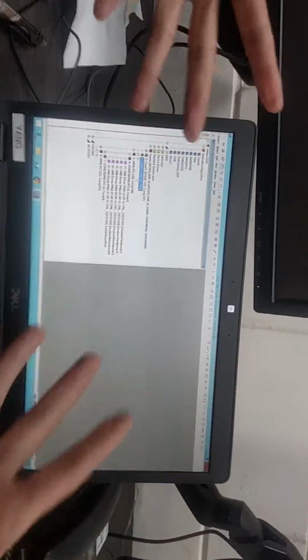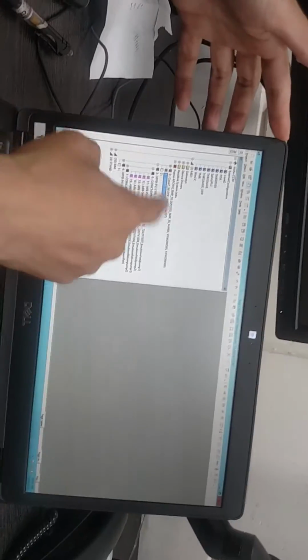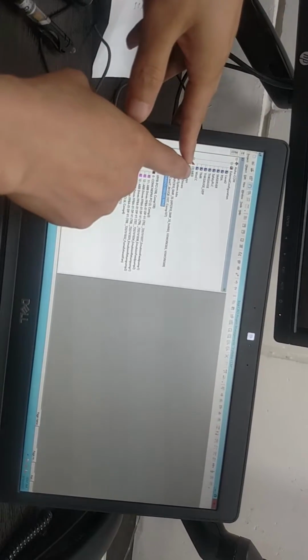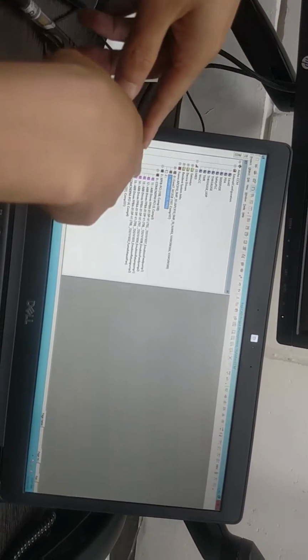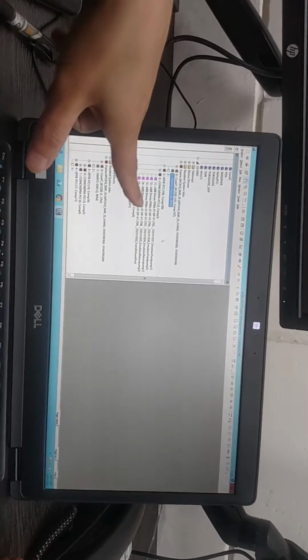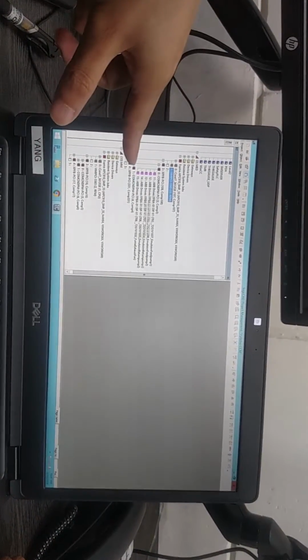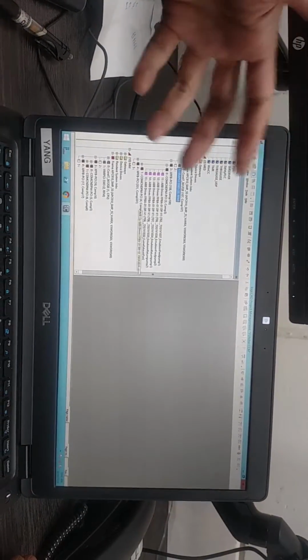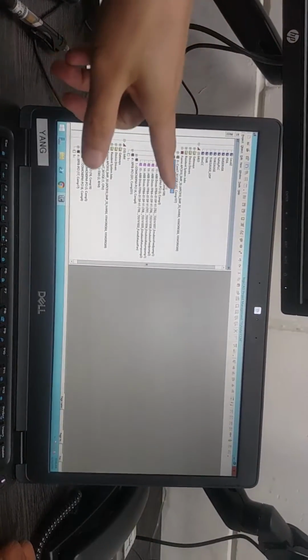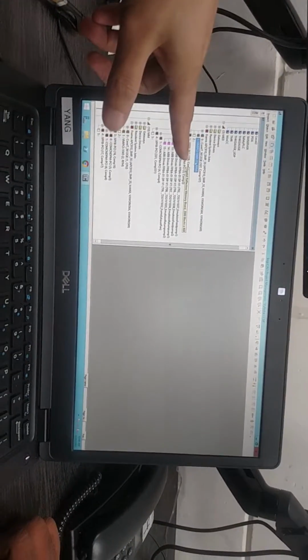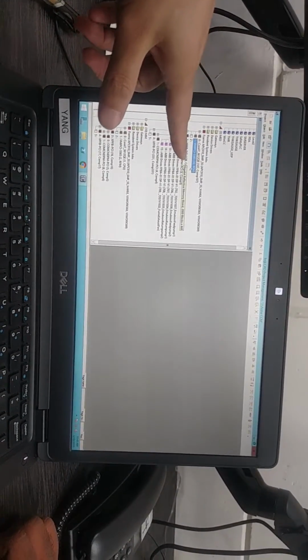All the hardware connections are individual. These drives are connected with the media PLC, and if another PLC wants to use the signal of this drive, we can change the drive status or data or messages into an internal variable, change it to a reflect memory variable, and then use a fiber cable to connect them.